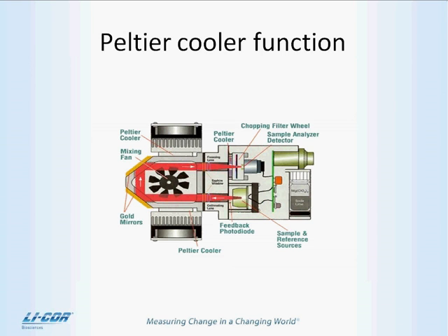You can tell whether the coolers are on by looking at the fans on the side of the sensor head. If they're turning, the coolers are turned on. If you've told them to turn and they're not, you may have a problem. Check your troubleshooting guide in the manual.